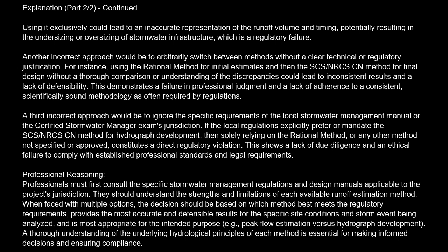A third incorrect approach would be to ignore the specific requirements of the local stormwater management manual or the certified stormwater manager exam's jurisdiction. If the local regulations explicitly prefer or mandate the SCS/NRCS-CN method for hydrograph development, then solely relying on the rational method or any other method not specified or approved constitutes a direct regulatory violation. This shows a lack of due diligence and an ethical failure to comply with established professional standards and legal requirements.